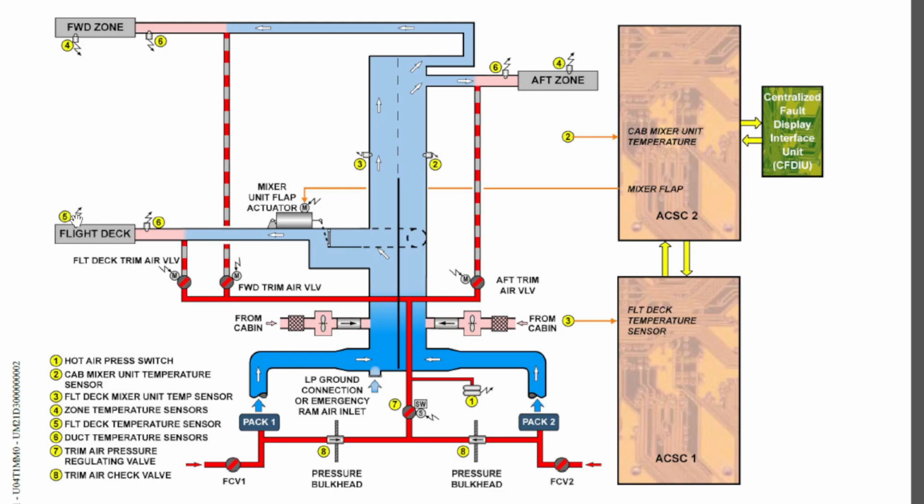The flight deck temperature sensor is located in the cockpit towards the rear CB panels, and the zonal temperature sensors are located on the lavatory and galley extraction duct.